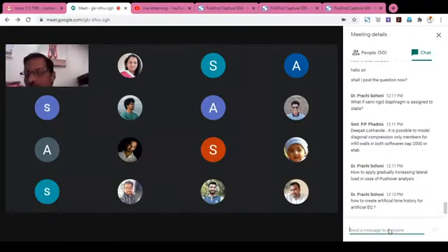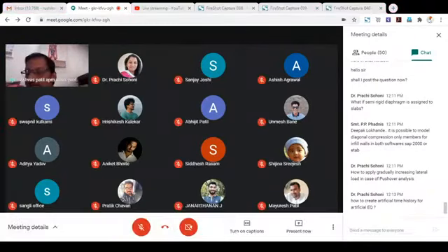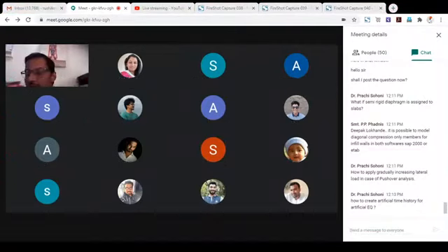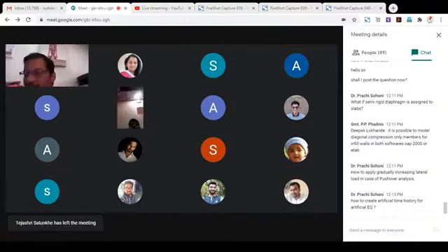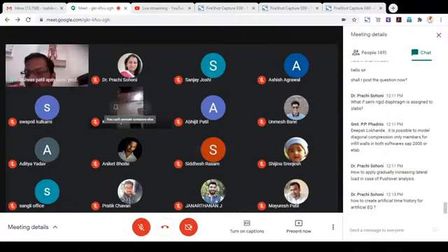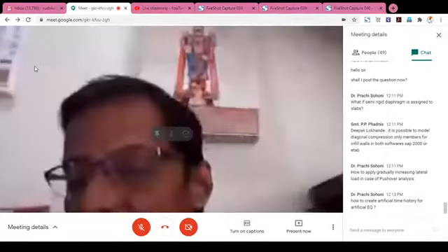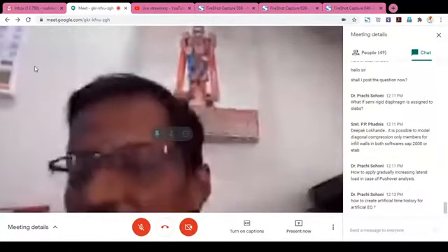But actually the question is when it is required to go for artificial time history. If the natural records are not sufficient, in the sense that the natural records are not giving the response as you require, then in that case go for synthetic. Then what kind of response you expect, that record must be available with you. If it is available, then we can perform this analysis.